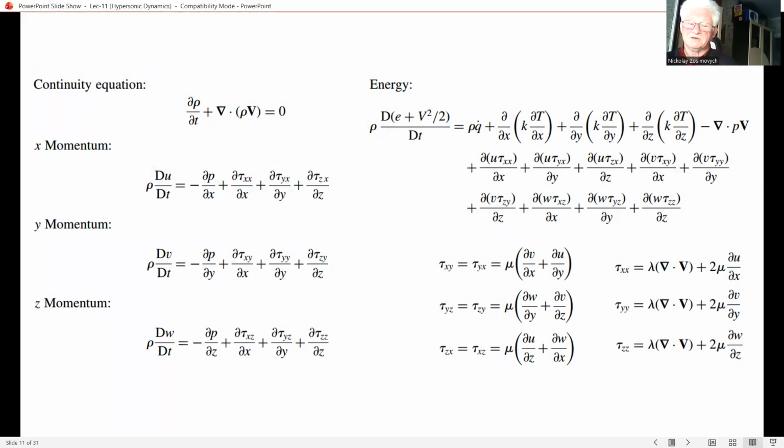So, in the general equations of motion for a fluid flow, viscous effects do not influence the basic principle of mass conservation. However, visualizing a moving fluid element, the shear and normal viscous stresses on the surface of the element result in stress terms that appear in both the momentum and energy equations. Moreover, thermal conduction across the surface of the element provides an additional mode of energy transfer, which appears in the energy equation.